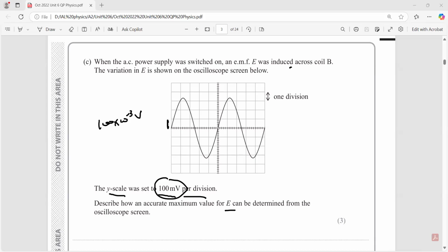What will be the uncertainty? In that case, that number you will take as the uncertainty. For example, if it is written 50 plus minus 0.1 centimeter, then you will take this value as the uncertainty. But for instruments, when it is mentioned, the uncertainty is half of the resolution of the instrument.